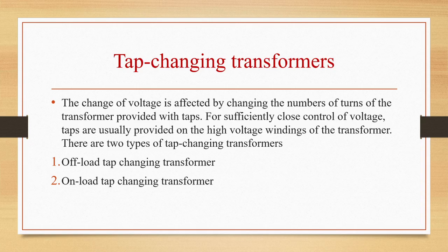So various tappings will be provided so that we can give the required value of voltage to the device which is getting connected to the transformer. So these are tap changing transformers. In that we have two types: off-load tap changing transformer and on-load tap changing transformer.